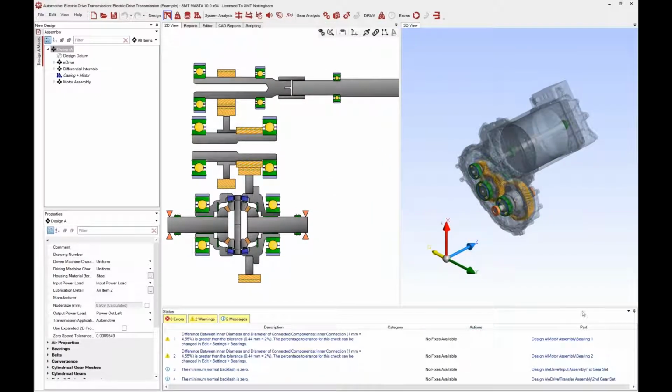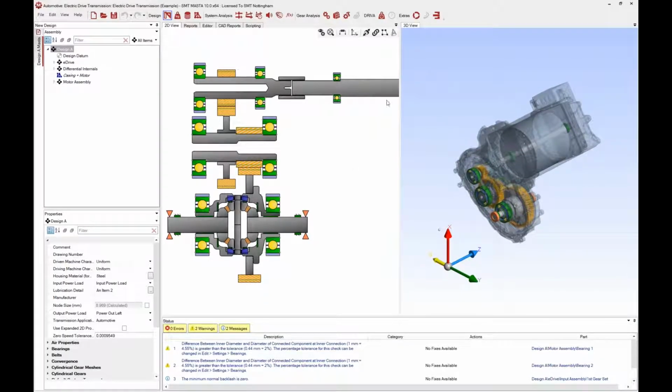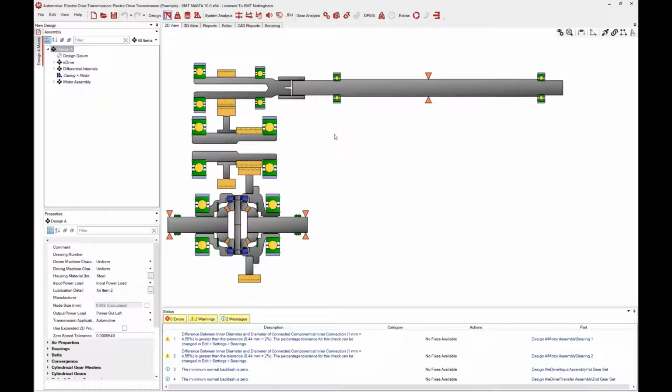And there you see we've been able to split the screen. And you can split this as many times as you wish. Obviously, it gets a bit confusing if you have too many screens showing, but you've got full customization over this. If you then want to reset your screen to how it normally would be, underneath the view drop down at the top of the MASTA window, there's this reset display option, which just takes you back to normal.